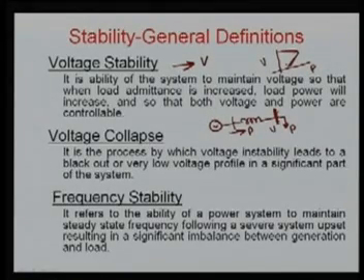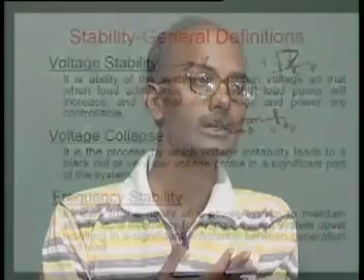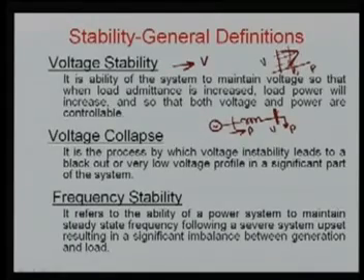What does it mean? It shows that for one power, let us suppose P naught, you have two voltages, one voltage here, another voltage here. Now, which one is your operating voltage? Which zone is stable, which zone is unstable? You can see the topmost, when the power is increasing, your voltage is decreasing, that is obvious. But in the lower portion, below the nose point, if your power is increasing, voltage is increasing. So, this is a reverse one.